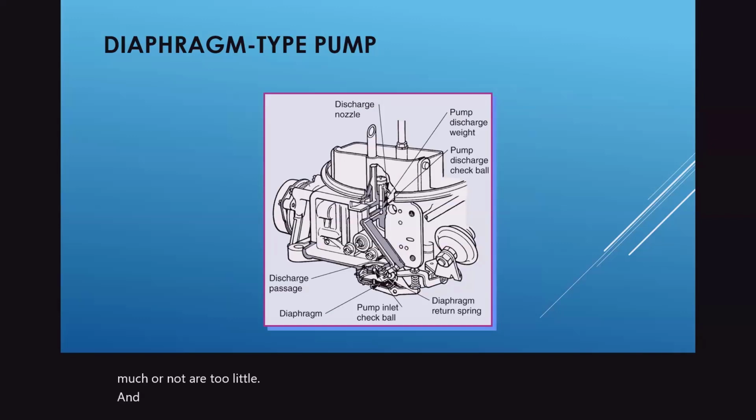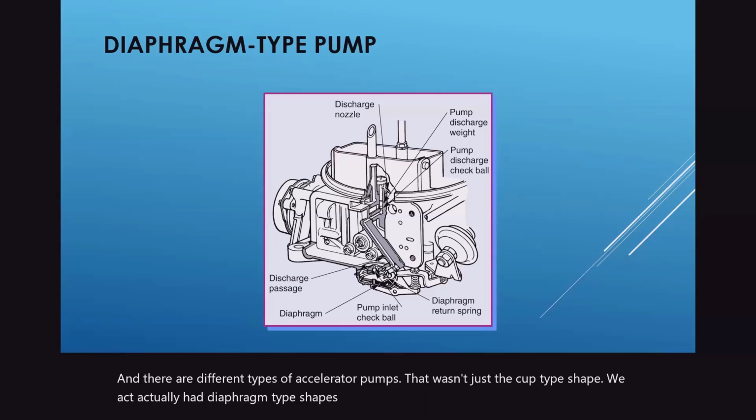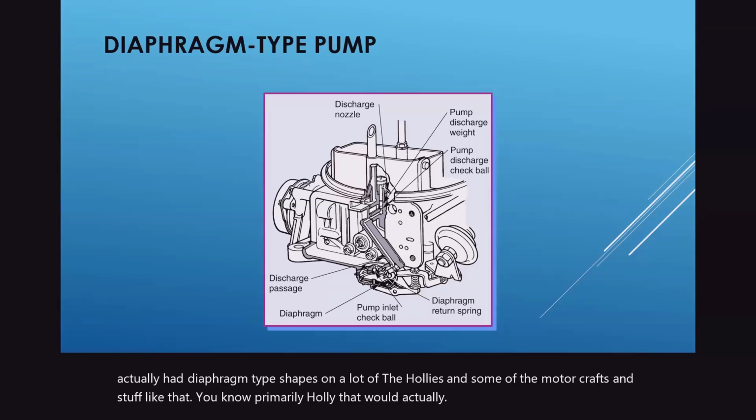And there are different types of accelerator pumps. It wasn't just the cup type shape. We had diaphragm type shapes on a lot of the Holleys and some of the Motorcrafts. Primarily Holley, that would pump the extra fuel that it needed.